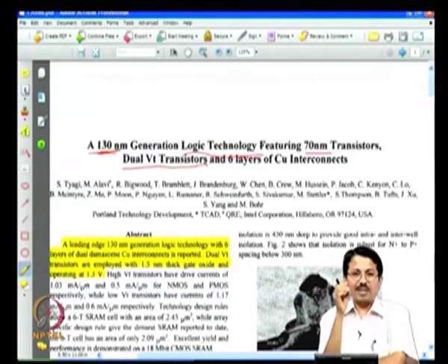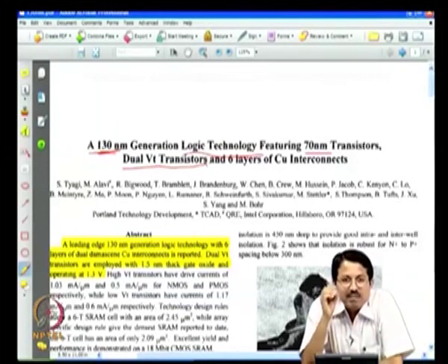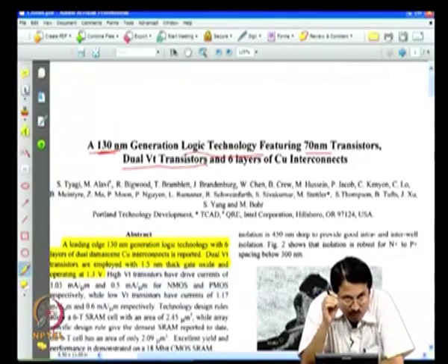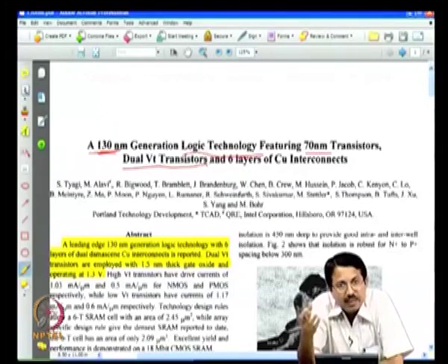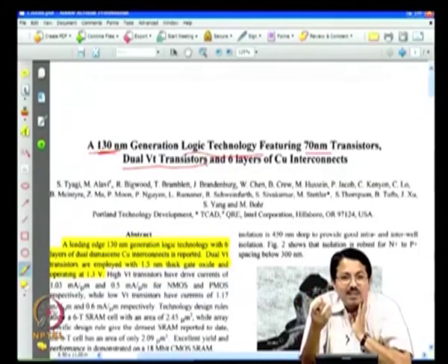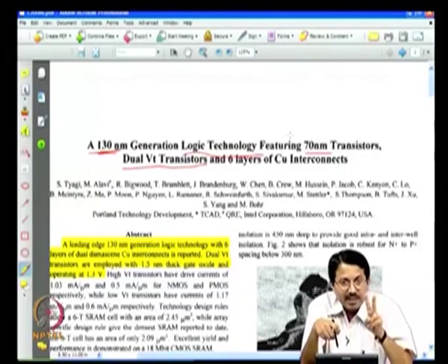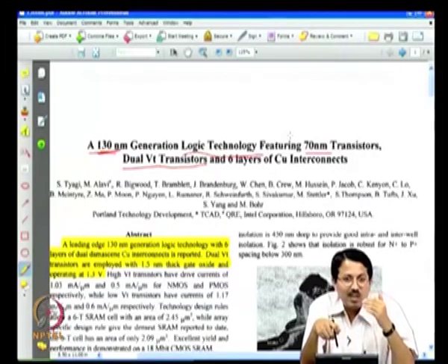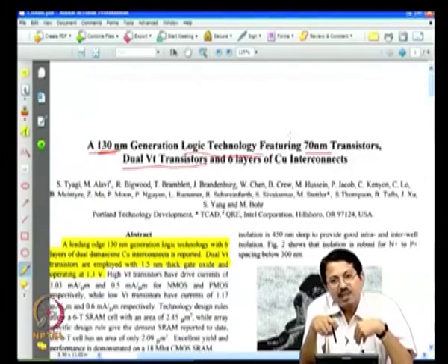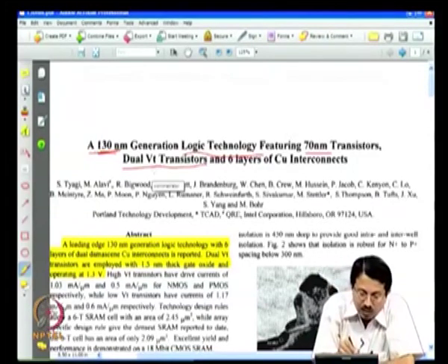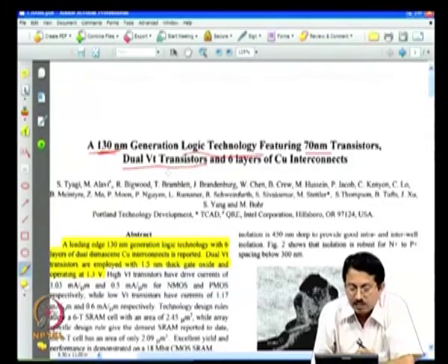It is important to make the transistors in the critical path very fast transistors, and hence make only those transistors low VT transistors, and others could be high VT transistors, right. So, as a result of that you get a very fast chip as well as a low power consuming chip. In other words, here you have two flavors of n channel transistors and two flavors of p channel transistors. One is called a low VT transistor and the other one is called a high VT transistor, and hence it is a dual VT transistor technology.